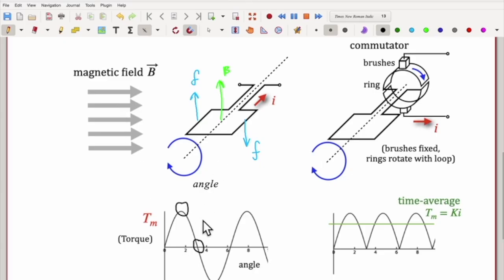And then what happens in this case is if you keep rotating the coil even more, the torque reverses direction, and you end up with a counter torque that drives it back to an alignment to here. This corresponds to the intuition you might have that these two things want to align their magnetic fields, and as you rotate this back and forth, it will drive it back to this point.